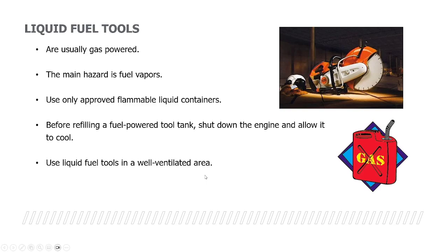Liquid fuel tools are usually gas powered. They could be diesel. The main hazard is the vapors. Okay, the fuel vapors coming off those. Only use approved flammable liquid containers. Before refilling a fuel-powered tool tank, for example, shut down the engine and allow it to cool.